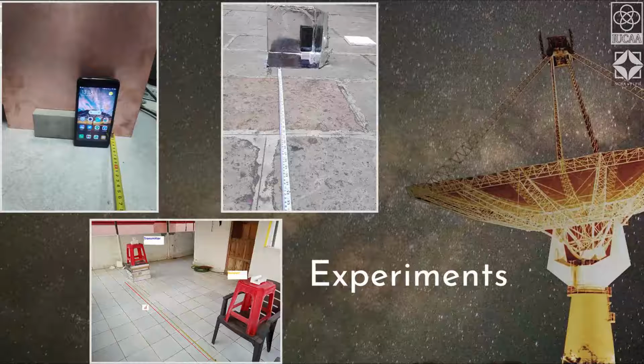You can place that cardboard just next to your transmitter, but the distance needs to be lambda by 4. Generally Wi-Fi systems operate at 2.4 gigahertz, which corresponds to a wavelength of around 12 to 12.5 centimeter.